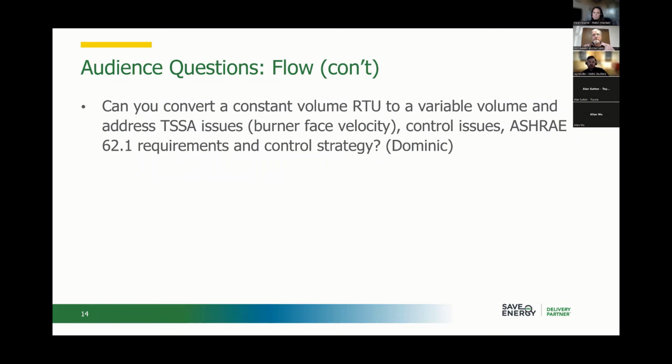Well, and I think we've seen a number of these projects, but I think to your point, Vern, and what you mentioned before on that systems approach, it starts with that understanding around what your flow requirements are. And that includes the different regulations, or what is happening in the space. Are there fumes that need to be evacuated even when people may not be present, and matching that. And then working with the good installers to maintain that face velocity coming out of the diffusers, and make sure that you're still getting that proper mixing in place. The key is you always want to make sure your processes are satisfied. Well, in an HVAC system, we're the process.